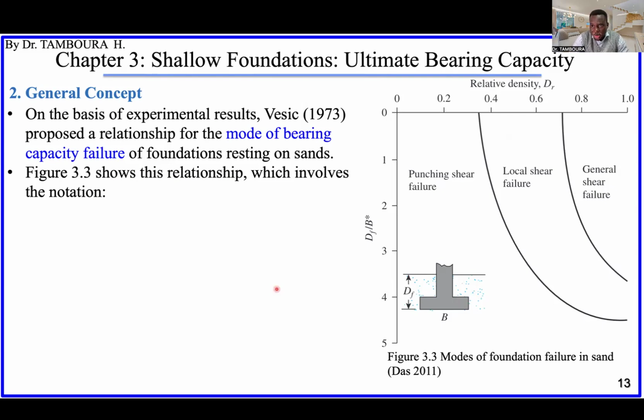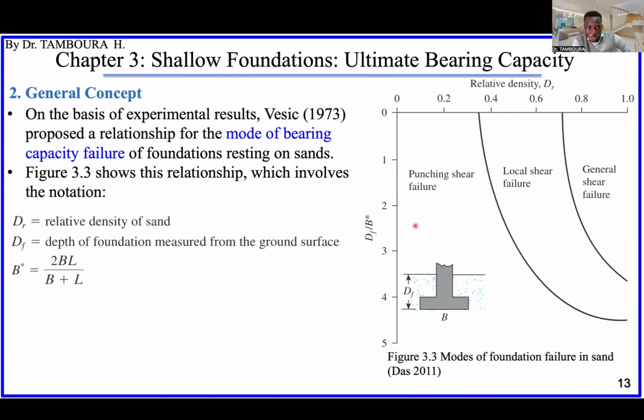there are some norms about the definition, even the definition of shallow foundation. This ratio, in the case of the definition of Terzaghi, we will see later, should be maximum 1. It should be here. Okay, there are some limits depending on each country. The definition of shallow foundation. Okay, if the depth is larger than, maybe this ratio is more than 1 or 2, it is not shallow foundation anymore, right? But this depends on each country.